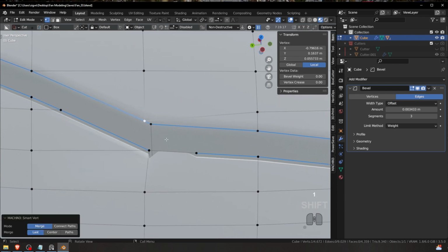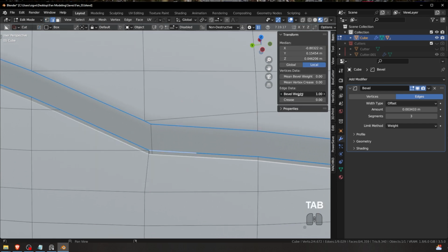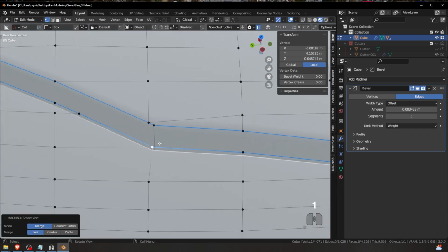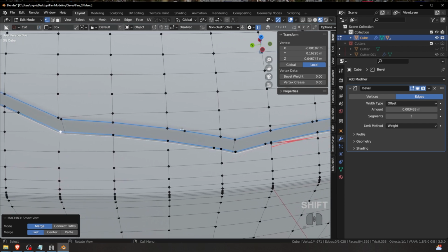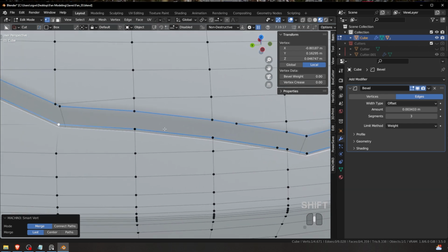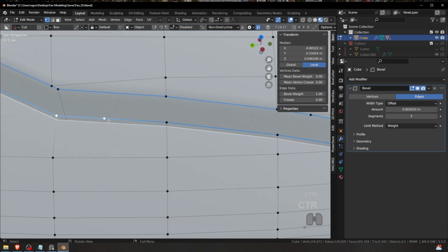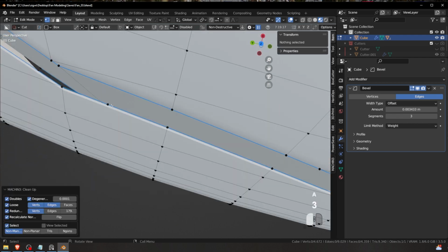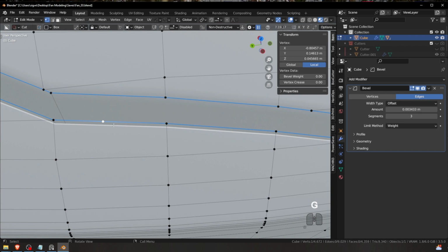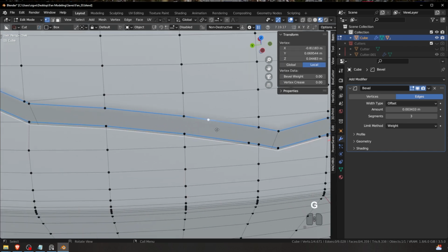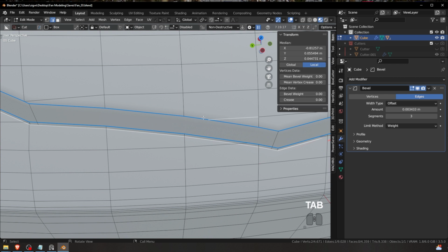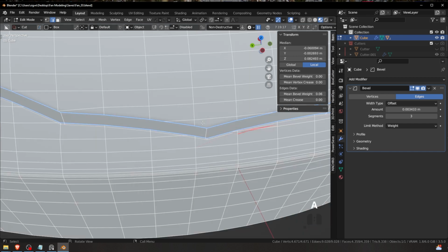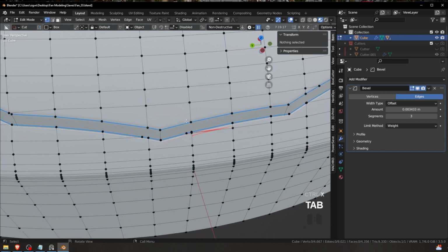There is just nothing for me to add. Just don't forget to add bevel weight to this, and don't leave edges like that in the center. You need to join it somewhere. There was a vertex. You need to make sure that it has some edge going towards it. I believe, no, this doesn't fix it. Okay, yeah, so just select it and Control X to dissolve it. So for example, this one has this edge going to it, so then don't dissolve it. You can actually dissolve the whole thing then. Maybe the whole thing in here. It's fine then.